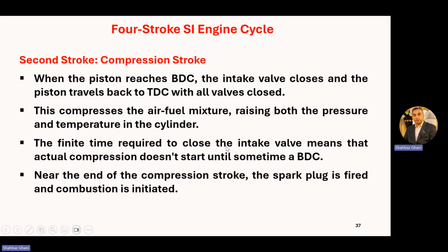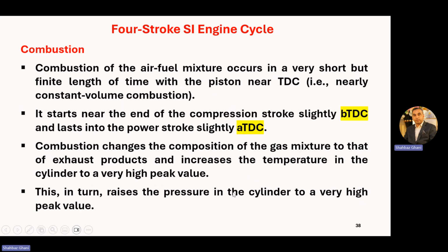Finite time required to close the intake valves means that actual compression does not start until sometimes after BDC. Near the end of the compression stroke, the spark plug is fired and combustion is initiated, as I explained earlier. Now, spark plug has given the spark and the combustion started.